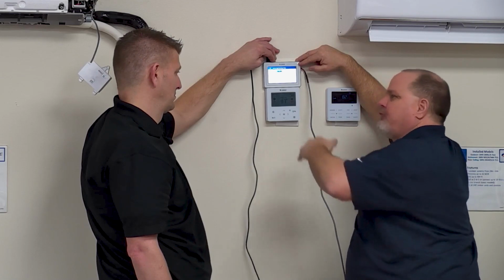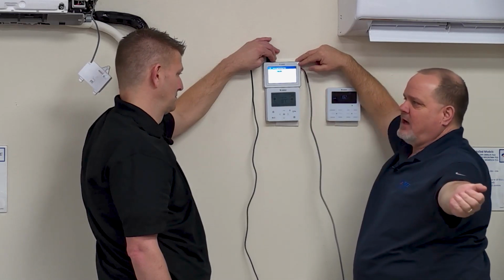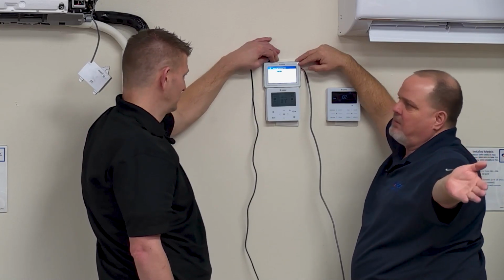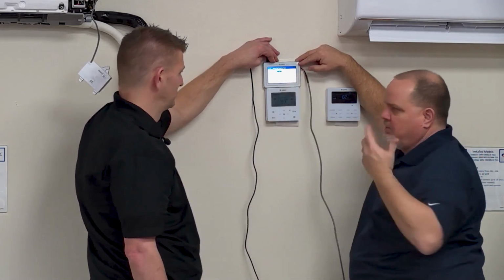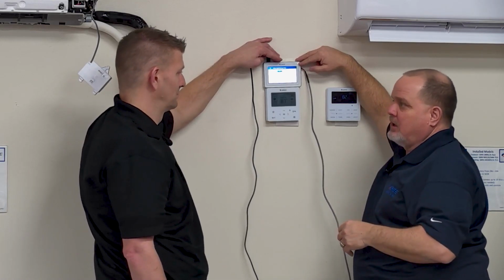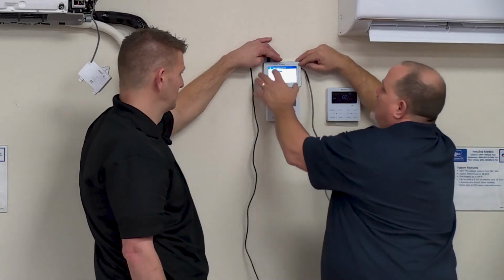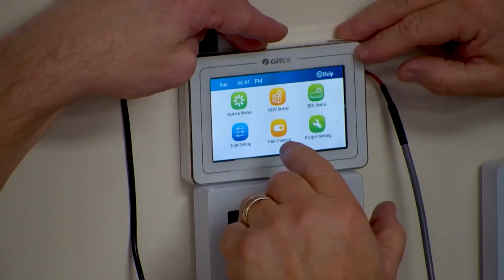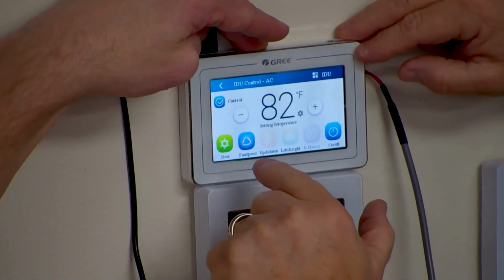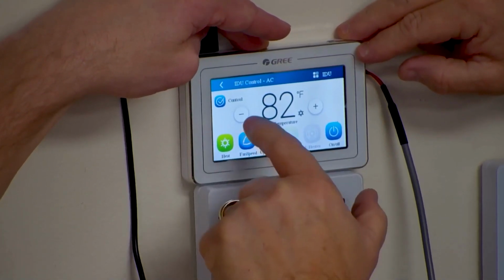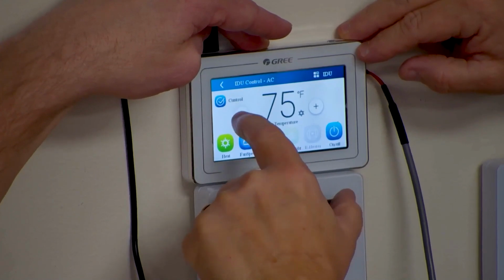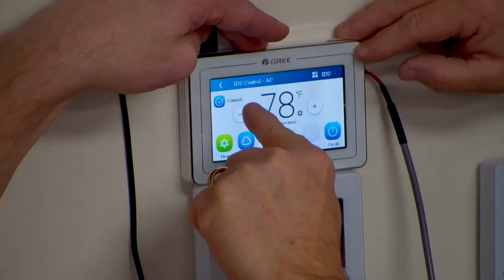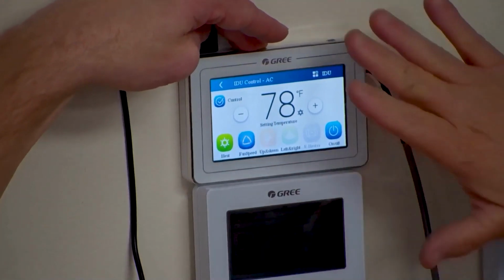But I need that free flow of liquid to go out the other side. I really don't want to be metering refrigerant into my liquid line going back to my outdoor unit from my indoor unit. So that EEV should be wide open or fairly wide open in heating mode, right? So maybe we go to unit control and shut this down. Oh, wait a minute. Hold on. Before we do that, remember, I got to hit the check mark to command it. So while you hold that up there,